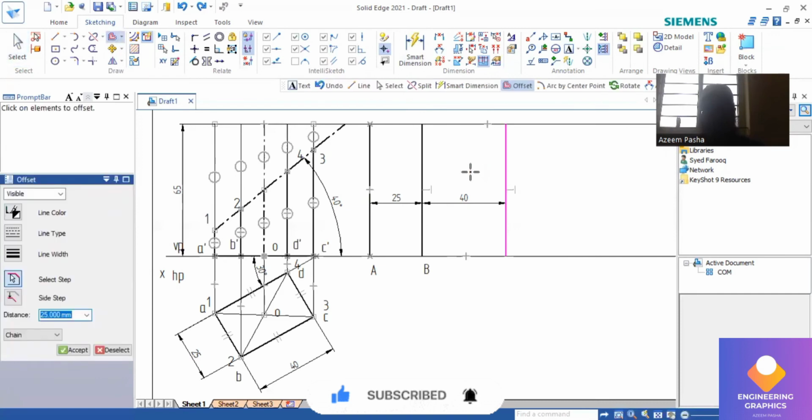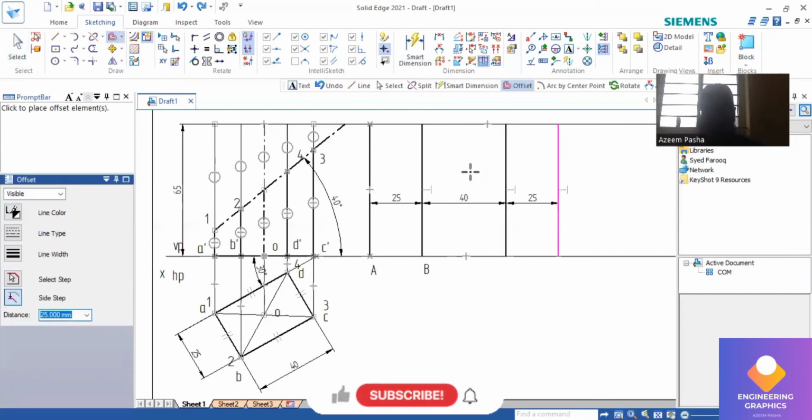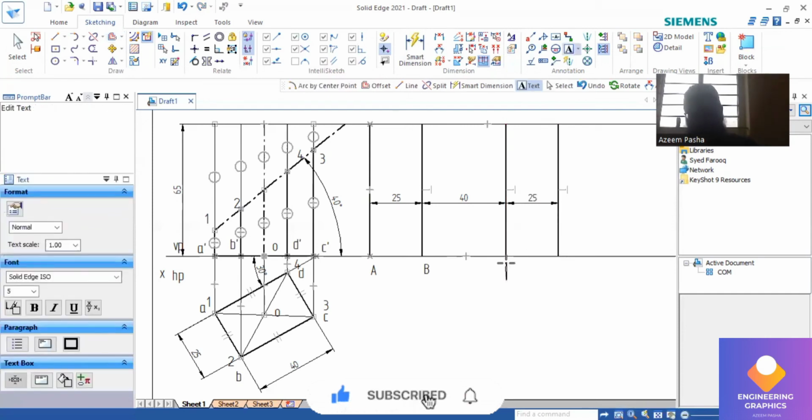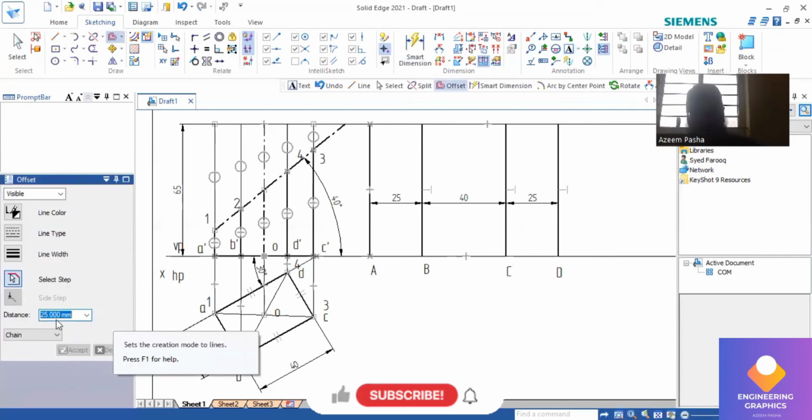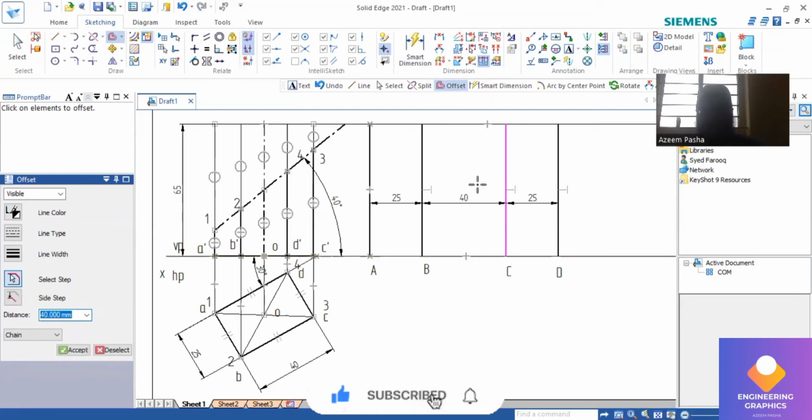You can draw the vertical lines here for a distance of 25 mm. Then again from D to A it is 40 mm. Use the offset command here, give 40, enter, and then click. You have to be careful when selecting the vertical edge here.